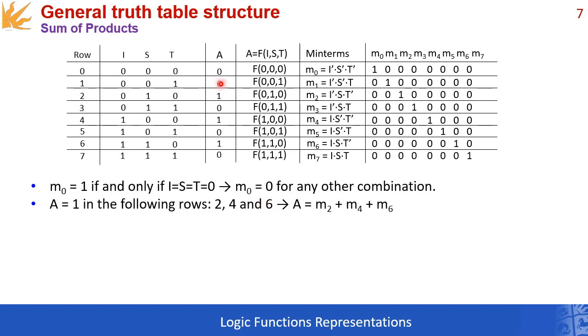And we know that because of the truth table that we previously constructed. Therefore, you can express the alarm function as the logic sum of these 3 minterms.